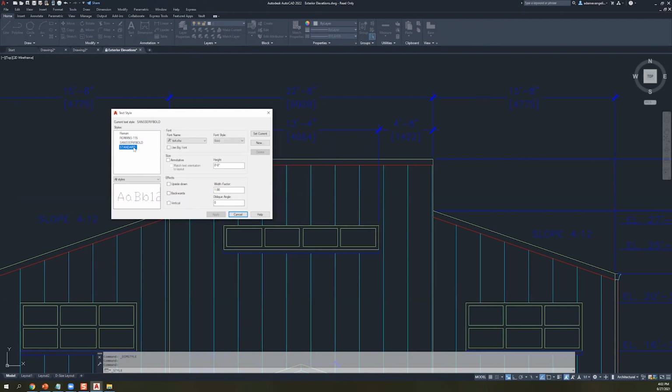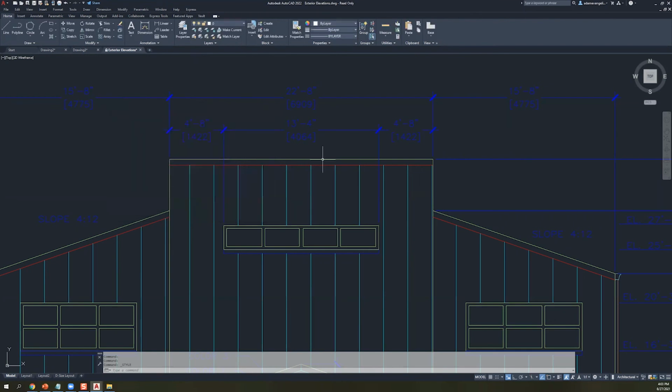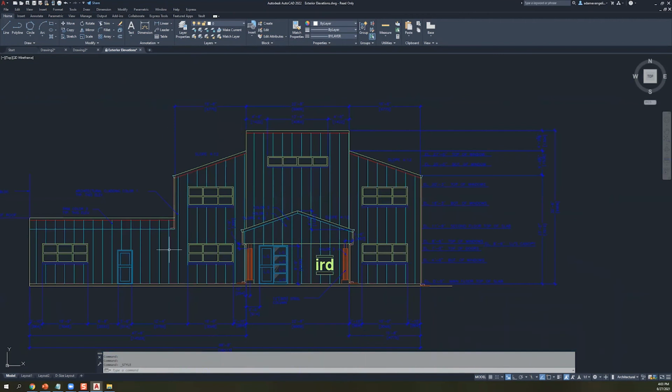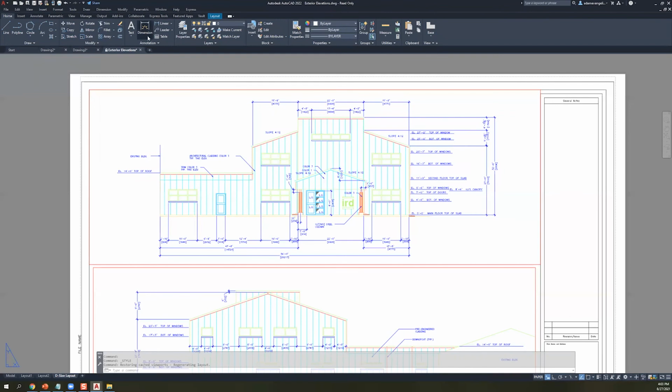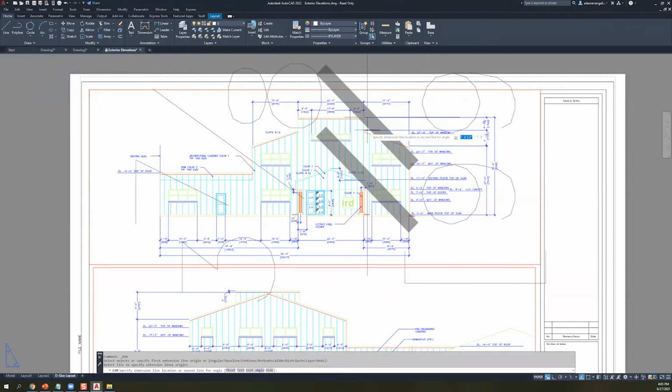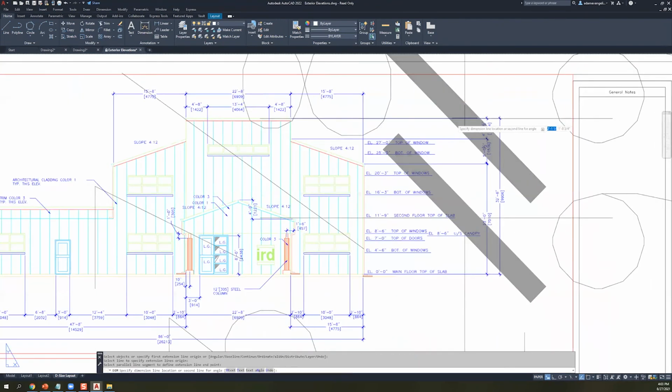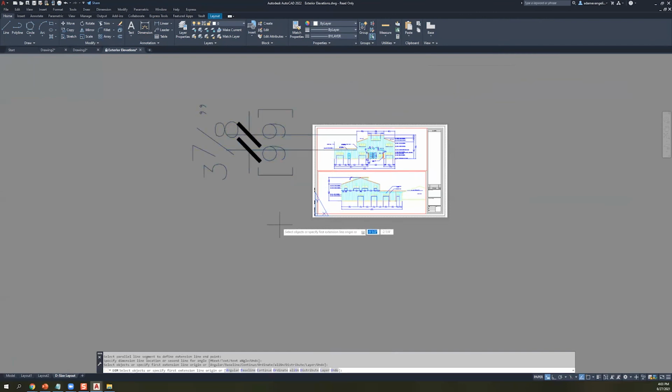I guess it's not terribly tall, comparatively, but depending on how you set it up, your dimensions themselves are going to be kind of large like that. And so something to keep in mind: if I were to go to the drawing from here and try to place those same annotations on here, they would be ridiculous, dude. Look at that. That's not an annotation I could use. That's huge. That's meant to be in model space. So that's why we have those dimensions over there, right?